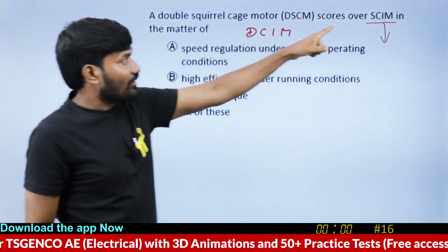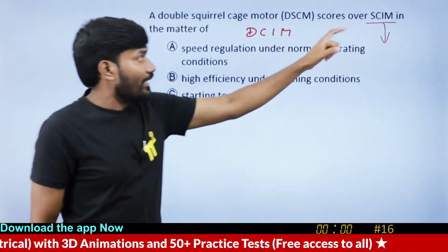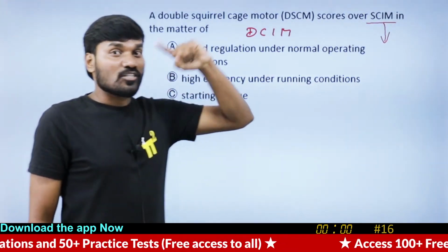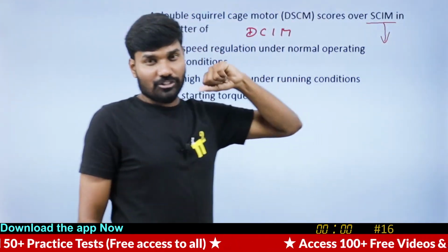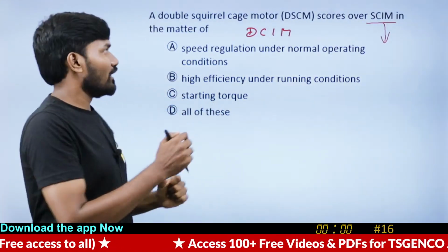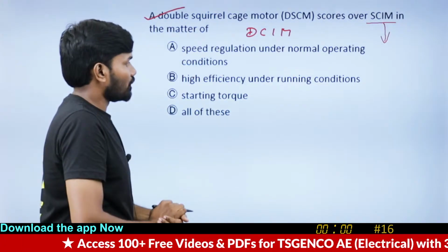So I want the cage rotor's running performance and less maintenance feature, but the slip ring motor's starting torque feature. An amazing blend of these two is the double cage induction motor, or double squirrel cage induction motor.